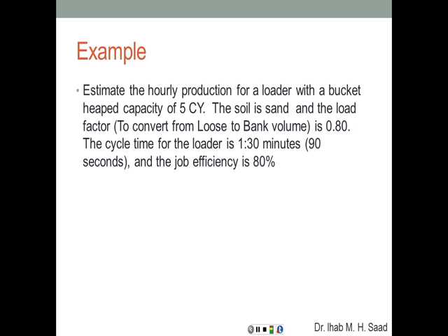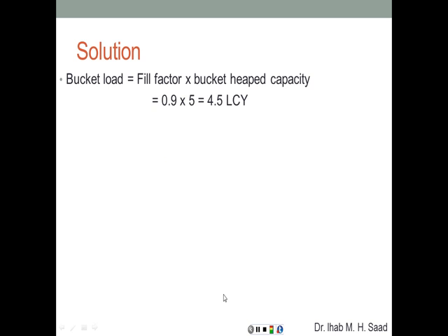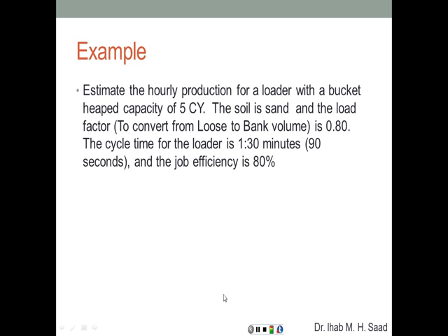The cycle time for the loader is 1 minute and 30 seconds, which is 90 seconds, and the job efficiency is 80%. So let's see how we're going to solve this. First of all, the bucket load is going to be equal to the fill factor times the bucket heaped capacity. The fill factor for that type of soil, based on this